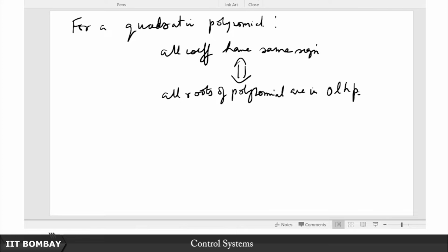If they are the same and there has not been any sign change in any earlier stage, because remember, at any earlier stage, maybe at the cubic stage, the 5th degree stage, the 12th degree stage of reduction, if there ever was a sign change, you can forget about all the roots being in the left half plane, because it is a necessary condition. Just because up until that point all the coefficients have had only positive values does not tell you that the roots will be in the open left half plane until you reach the quadratic stage. But if at any stage you violate that condition, then you are sure that you are violating the sign condition and therefore the interlacing property, and therefore this gives us a test.